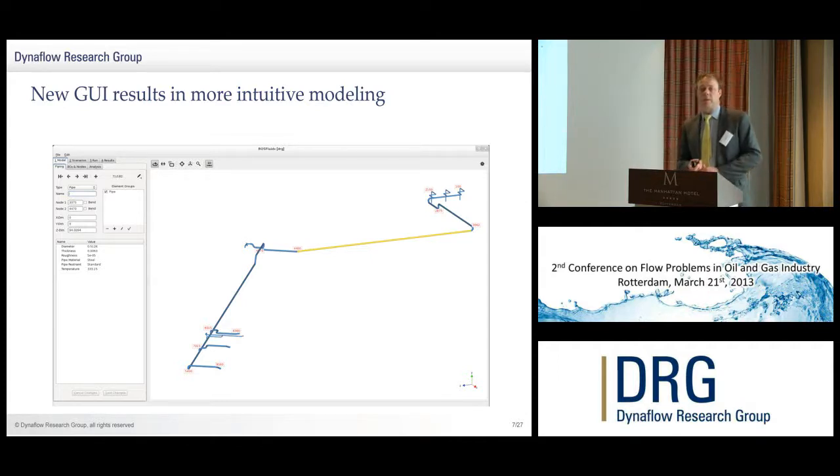Most method of characteristics systems around have more of a 2D network type of interface. This is particularly well suited for continuous analysis, for example, dynamic load analysis, stress type analysis, dynamic analysis of the piping system itself. As you see here on the left, you start off with the model, piping, boundary conditions, and analysis parameters. You continue with scenarios. You can enter different scenarios, and then there's a running tab, and then you will be able to post-process the information using the results tab.